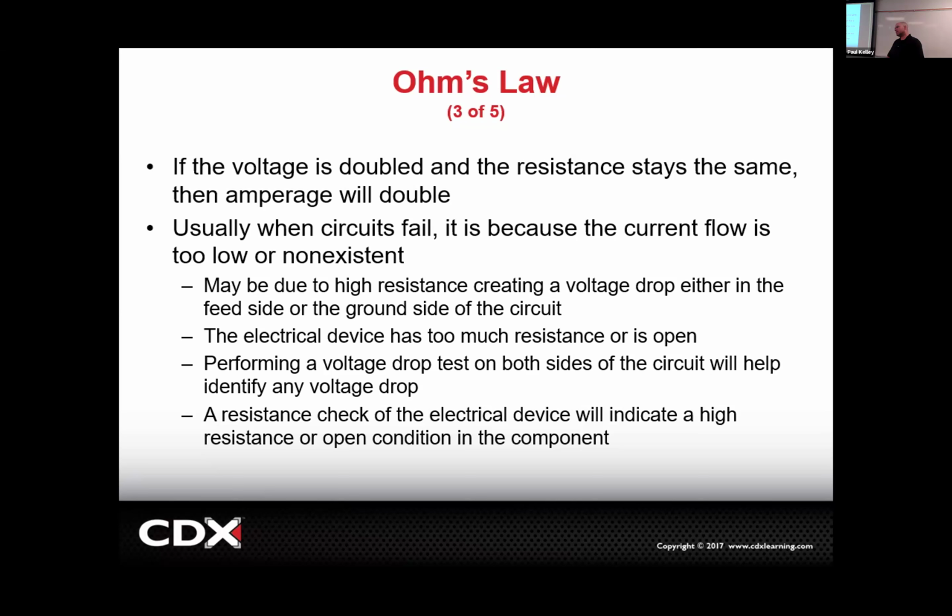But what if the bulb was dim? I think I'm going to have excessive resistance somewhere, but it's not going to be a full-blown open, right? I'm going to be maybe looking for 10 ohms or 100 ohms of resistance, but probably not 100 mega ohms, which is millions, right? So we can measure that in several different ways, but let's start actually at the bottom.